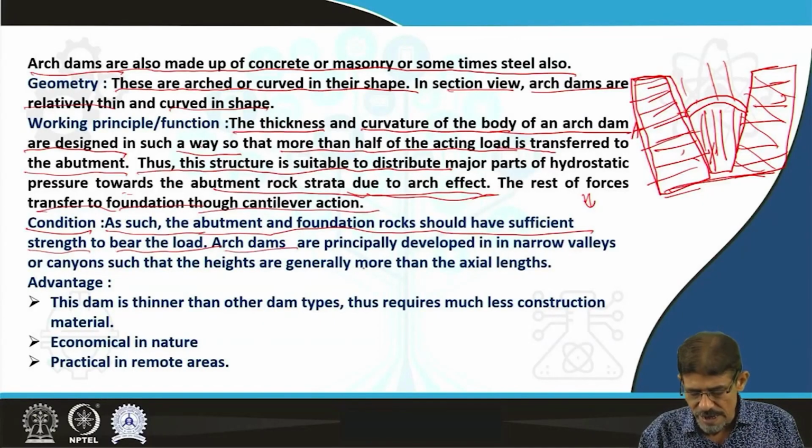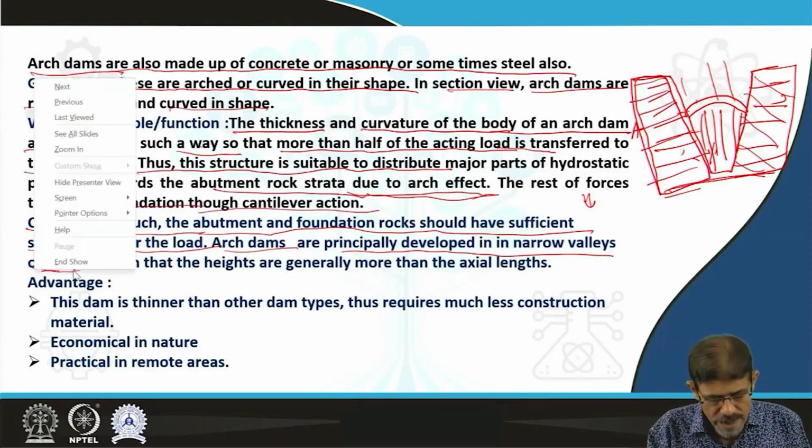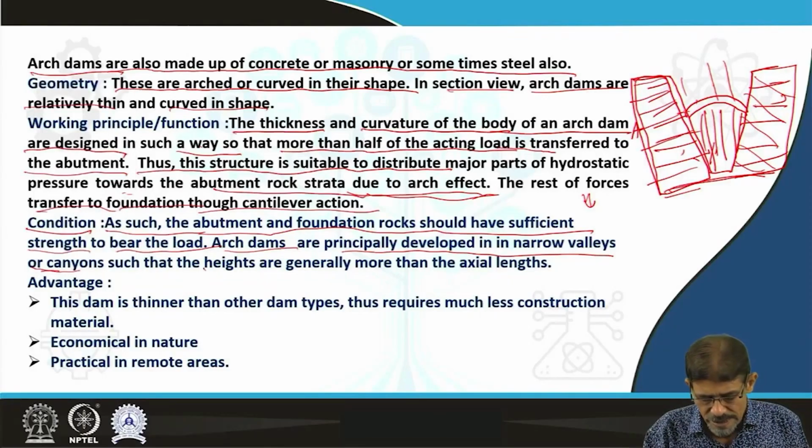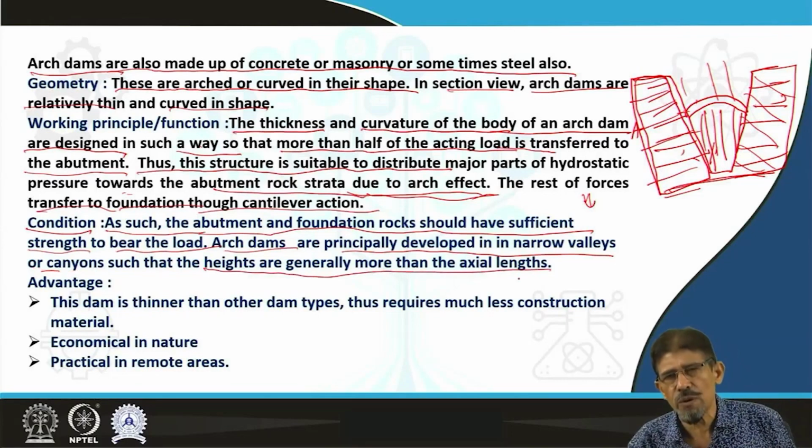The arch dam, as per principle, is developed in a narrow valley to avoid unnecessary use of more material. Narrow valleys are canyons where the heights are generally more than the axial length. Therefore, we generally prefer narrow canyons or valleys.